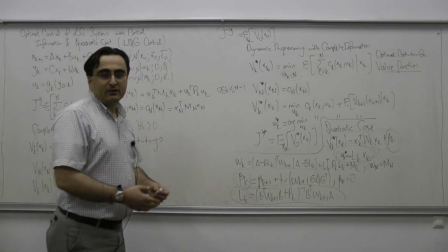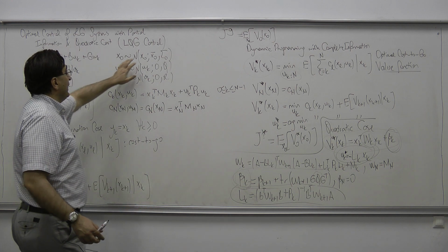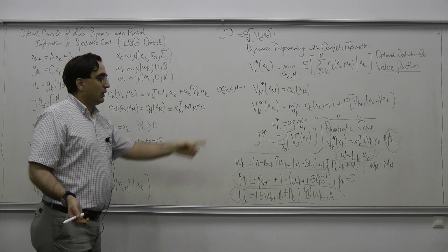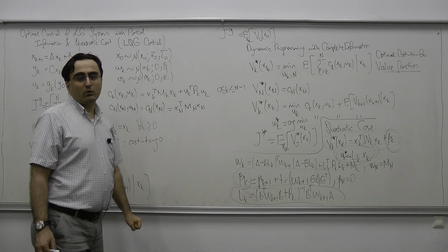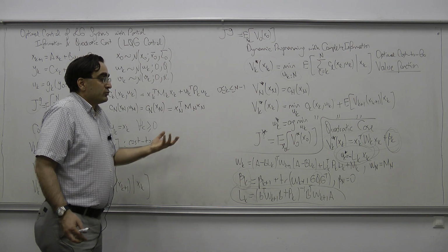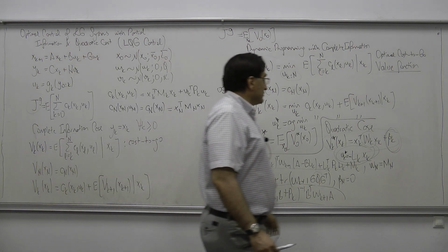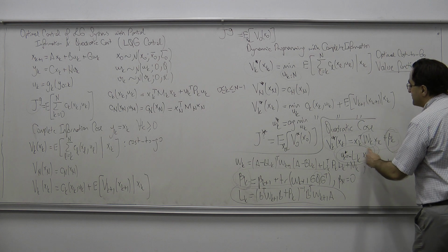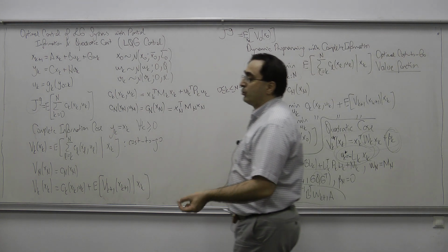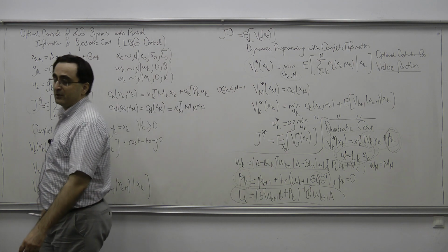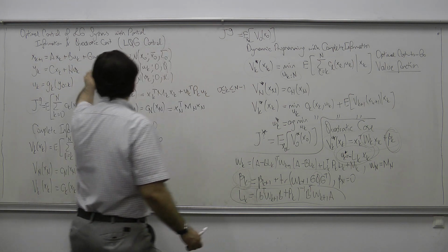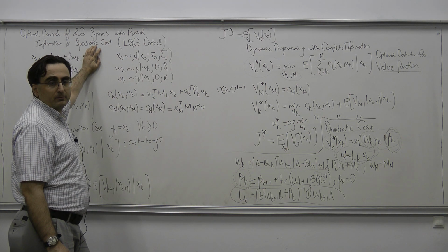That means that even if I take this covariance Q equal to 0, I will get exactly the same control feedback policy. Okay? So what does that mean? That means that this optimal feedback policy is also going to be the optimal feedback policy when I don't have any process noise in the system.